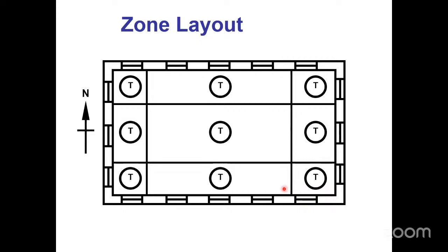9 zones is about the minimum that I'm going to have because I need to have one for the core because that guy's cooling all the time, no matter what. I need to have north be separate from the other directions because he never gets any sunlight. East gets sunlight, but not the same times as south and west, right? So east, south, west, and north all need their own. Interior needs their own. Now I'm up to 5.